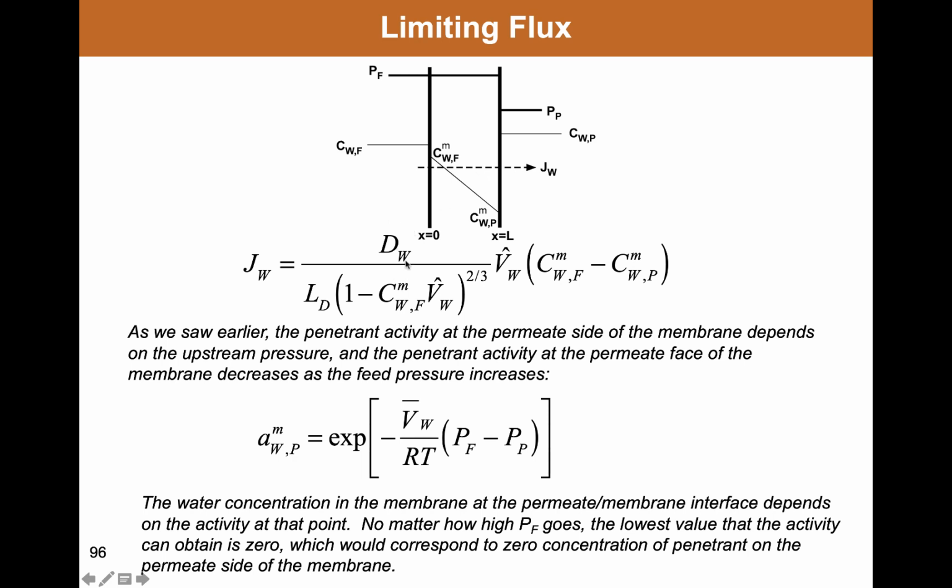We always use W because we're thinking back to the desalination application. LD is the dry thickness of the membrane, and then the concentrations of water in the membrane at the feed and permeate side. You'd need a thermodynamic model like the Flory-Huggins model to calculate those based on the chemical potential of water or solvent in the feed and permeate side of the membrane.